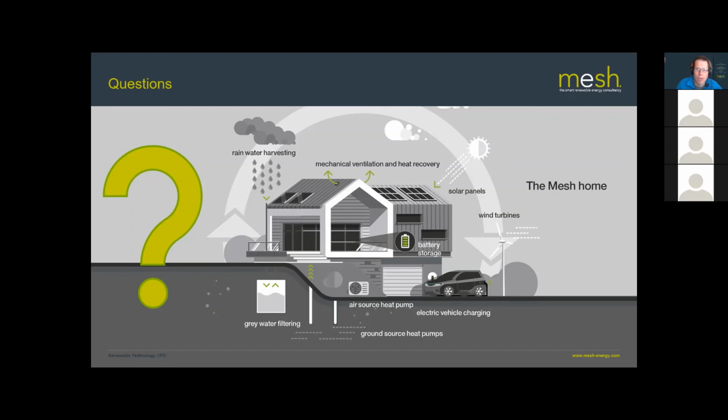Mohammed asked, would a higher voltage inverter allow thinner wiring? I'm assuming you're meaning on the AC side. Yes, I guess so. But generally speaking, you match the inverter voltage to the voltage you're going to be using around the house. The voltage from the panels into the inverter is set by the panel design and the string design. So that's where that comes from.